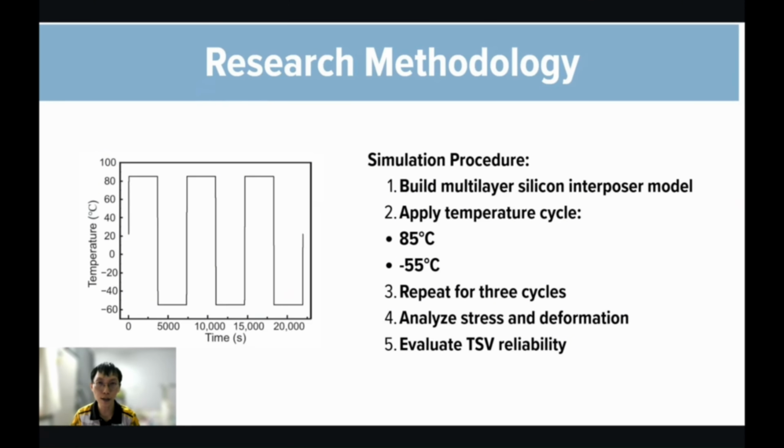This condition followed the industry reliability testing standard. The simulation was repeated for 3 cycles to observe how the thermal stress accumulates over time. The objective was to identify the most critical TSV locations and determine how the thermal cycling affects the long-term reliability of the interposer.